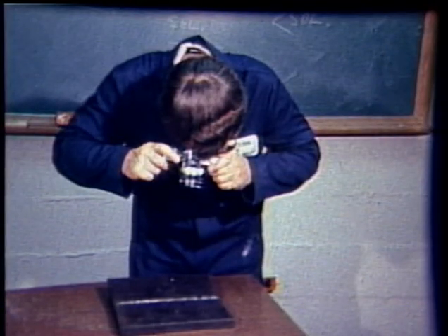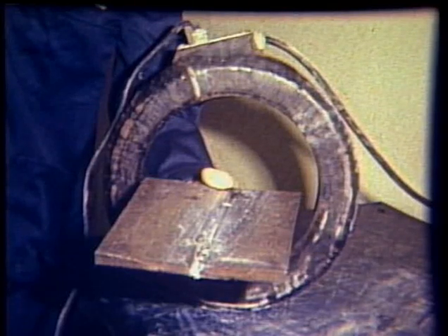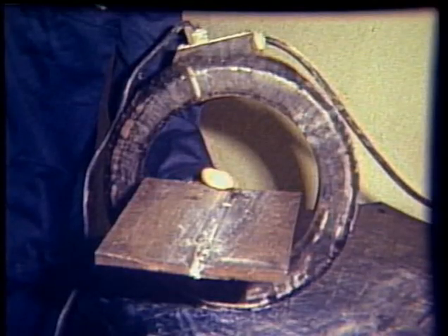After all reports are finished and visual inspection is complete, it may be necessary to demagnetize the part, since some components may retain enough magnetization to attract metal shavings and cause excessive wear during service operations, or it might make it difficult to perform further welding if the magnetic field interferes with the electric arc.